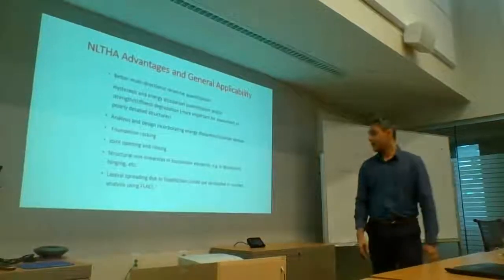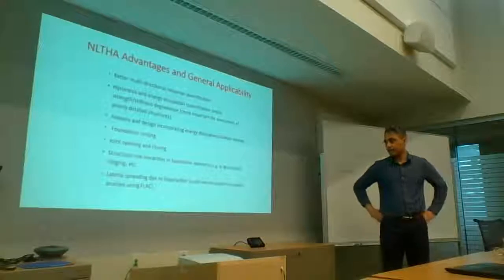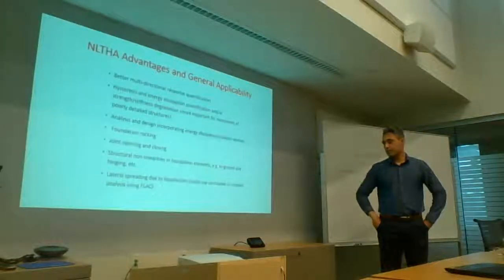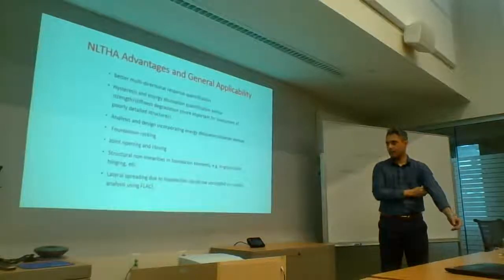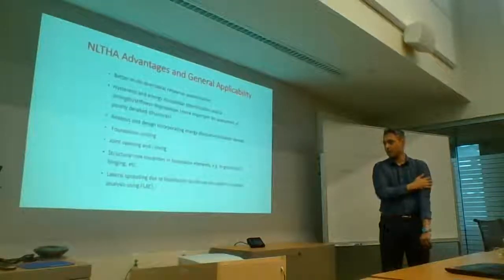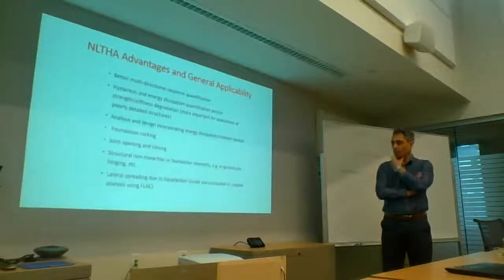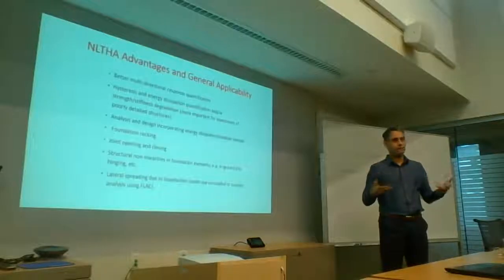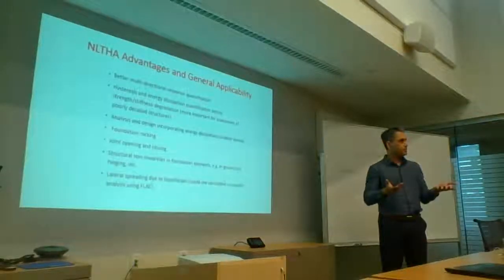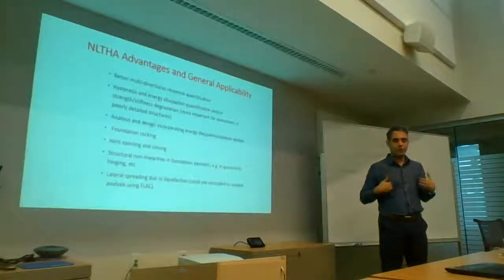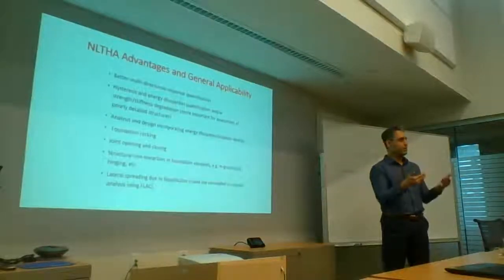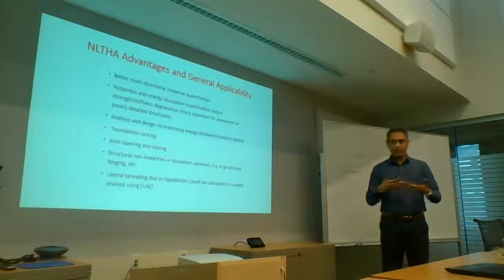Lateral spreading, FLAC is a finite difference software. It's used a lot on the soil side of things. Liquefaction is a very complicated phenomenon. I'll touch on it in a very simple manner in a little bit. But you can do coupled or uncoupled analysis. Uncoupled is when you just have the soil and you run it and you see how much the soil is moving. And then in a separate analysis where you have the structure, you go and you impose those soil deformations onto your structure.